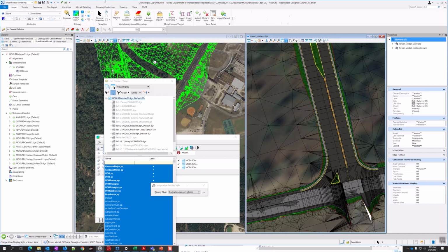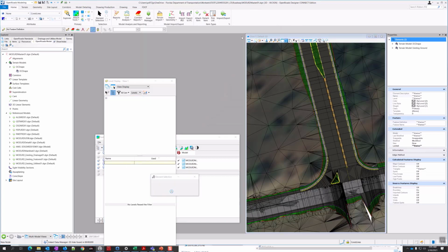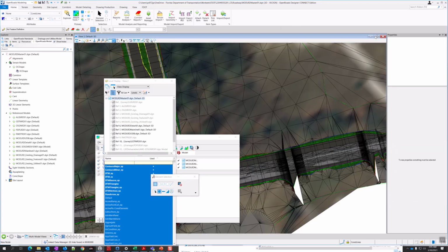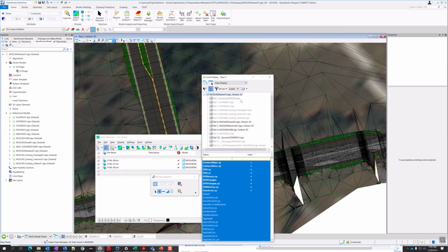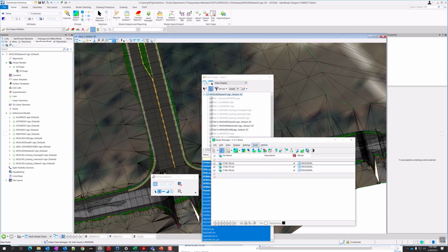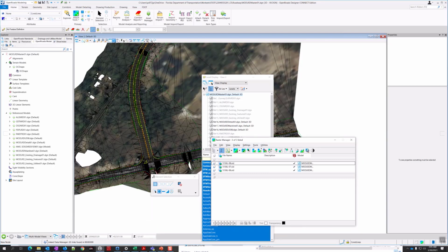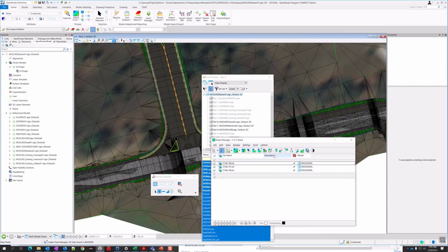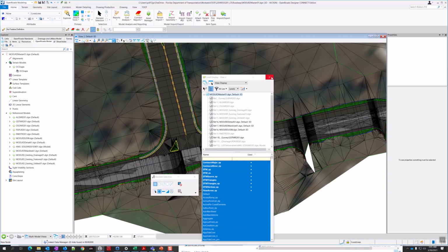We're still in the master model file. Make sure your 3D view is active. I'm going to go ahead and close the 2D view. Make this bigger. I'm going to turn off a couple levels here: construction lines and excess miscellaneous if needed. Now I've pretty much already cleaned this up, so all my construction lines are off. So I'll just leave that alone.